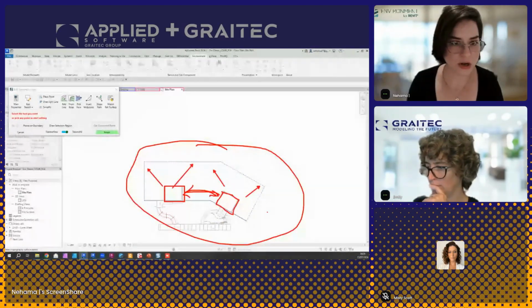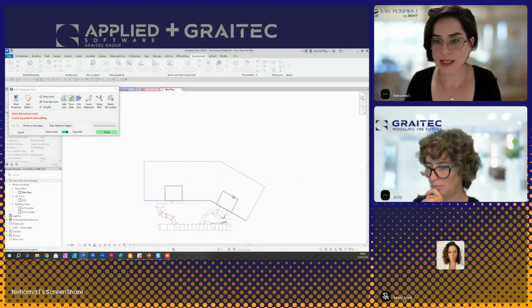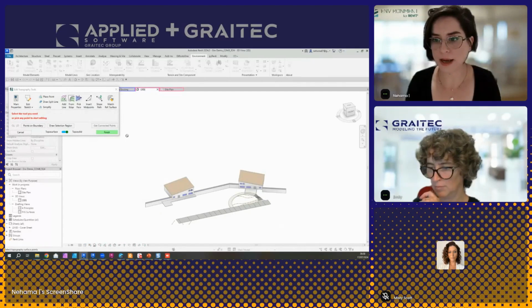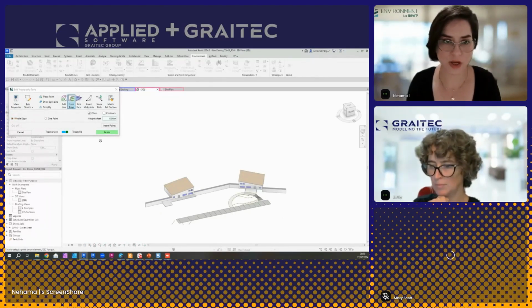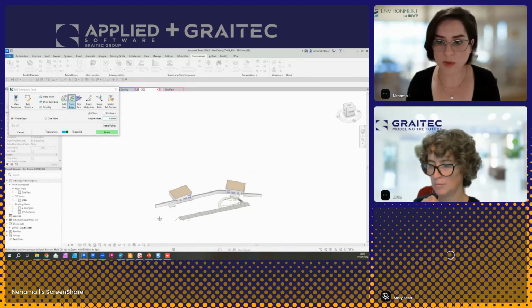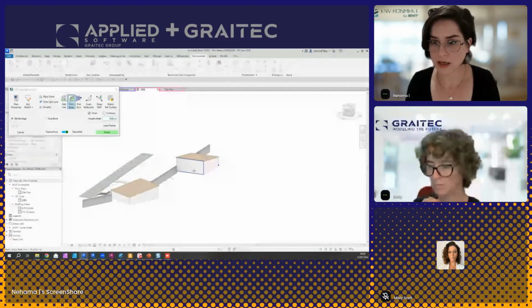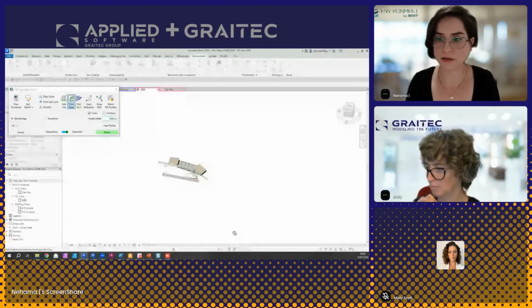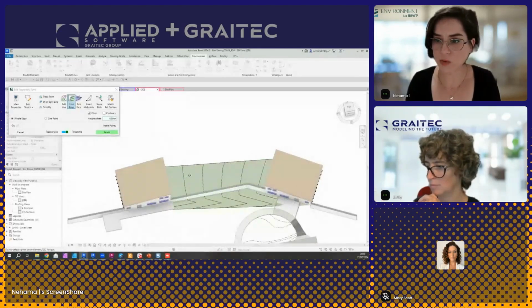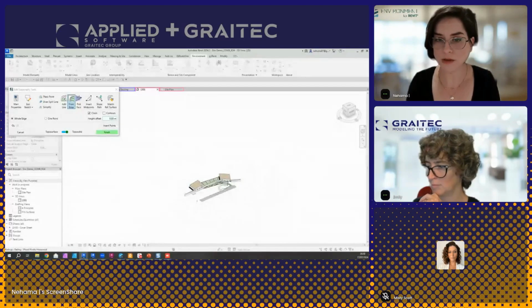And as a site engineer, as a landscape architect, I have a lot of things to consider. So instead of printing it and calculating it, I can actually use environment topography tools as the starting point and think from there. So here's an idea. I know I want to start from the buildings, so I'm going to use the from edge, and I'm just going to place some points on the edges of the buildings, right? And click on insert points, and I can already start to see the contour lines created between them. So as a landscape architect, that tells me a lot.